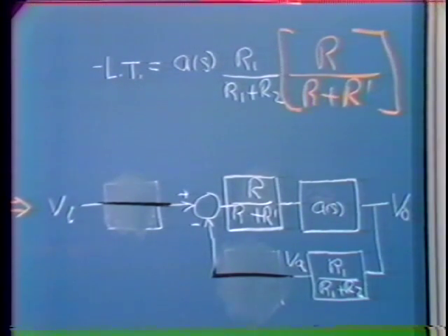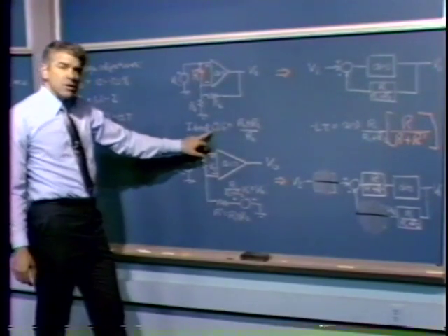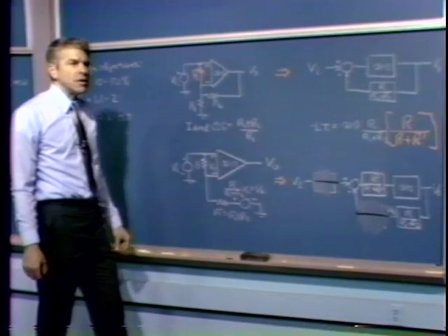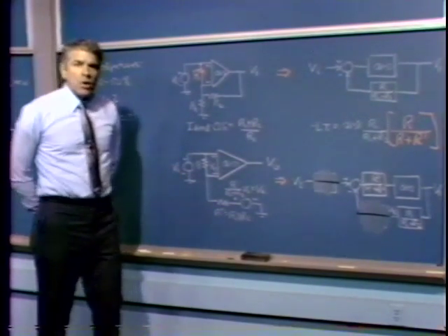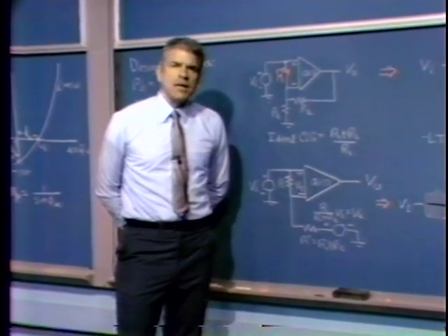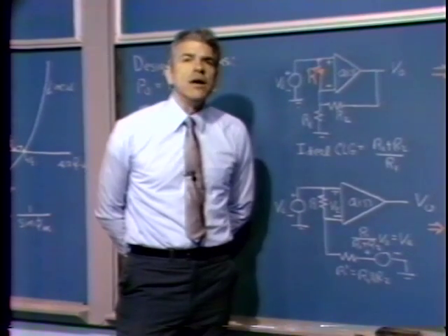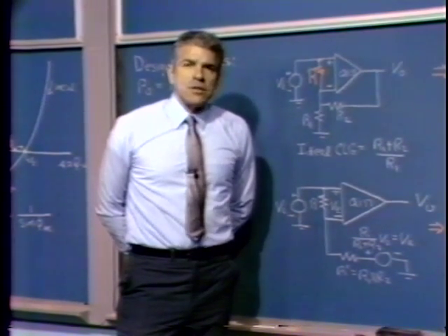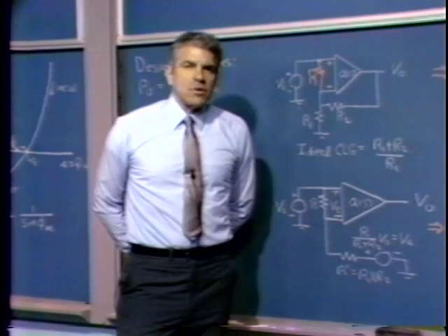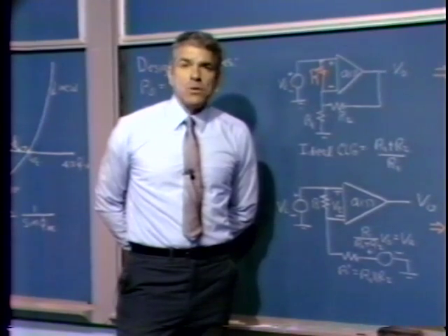And so if we had a system where we found that the system was inadequately stable, for whatever ideal closed loop gain we wanted, we'd be able to improve the stability by adding this one resistor. This is actually fairly frequently done. What we find out is that there are certain operational amplifiers sold, for example, that are not guaranteed to be unity gain stable. In other words, if we wrap feedback from the output of the amplifier back to its input, just put a wire from the output back to the inverting input, such amplifiers are not guaranteed to be stable. If they are stable under those conditions, we speak of them as being unity gain stable. What we really mean is that they're stable in a loop that has an F equal to 1.